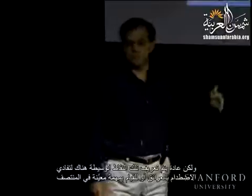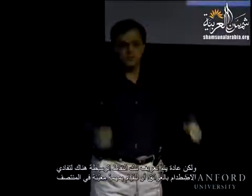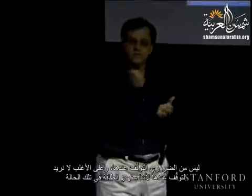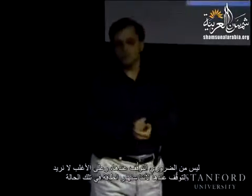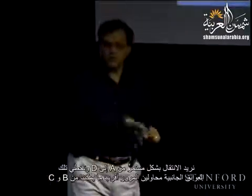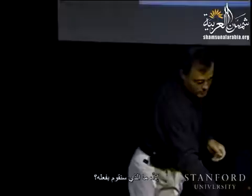But usually those intermediate points are introduced so that we don't collide with obstacles or so that we can achieve certain tasks in the middle. It's not necessary to stop at them, and we probably don't want to stop at them because we're wasting energy. So we want to go continuously from A to D, avoiding those obstacles on the side, going as close as possible to B and C. That's usually the goal.